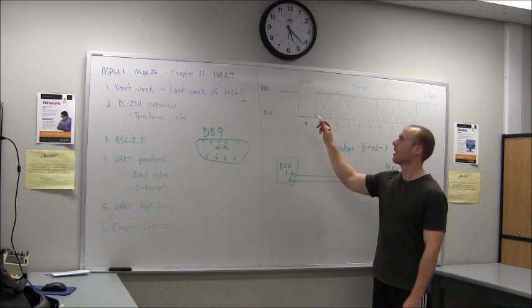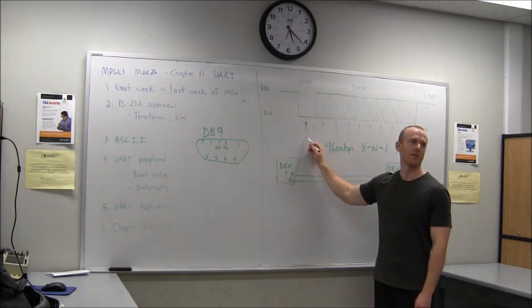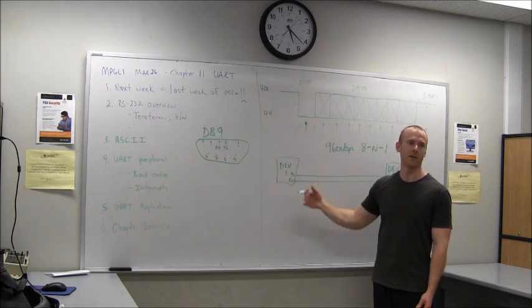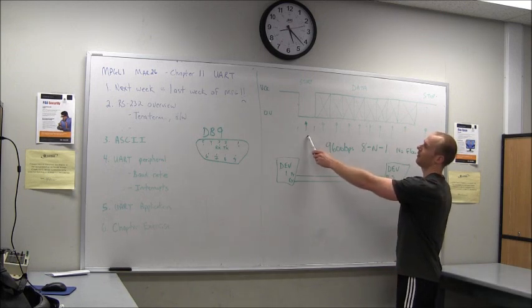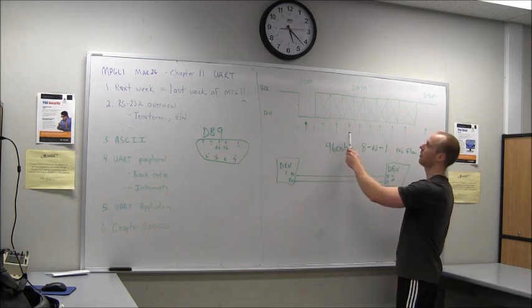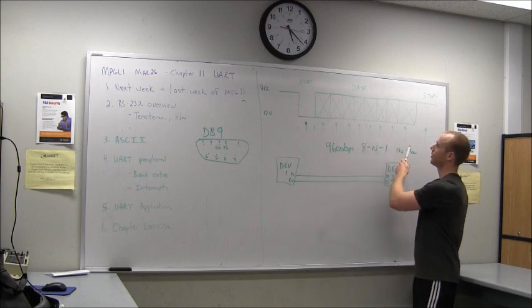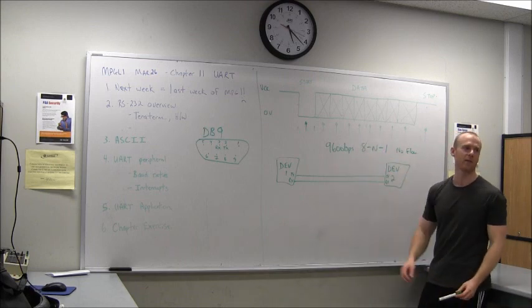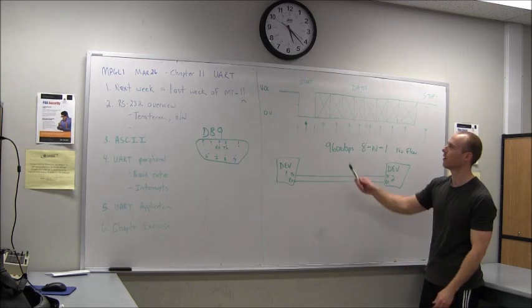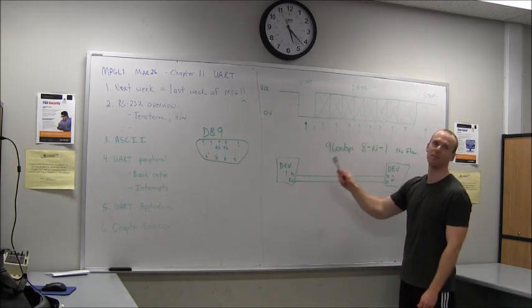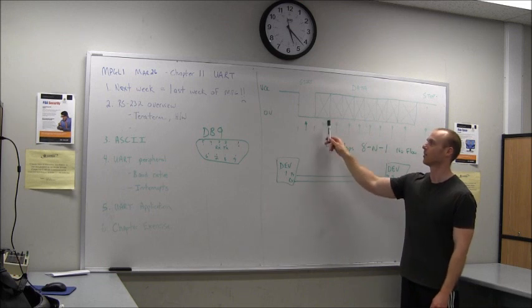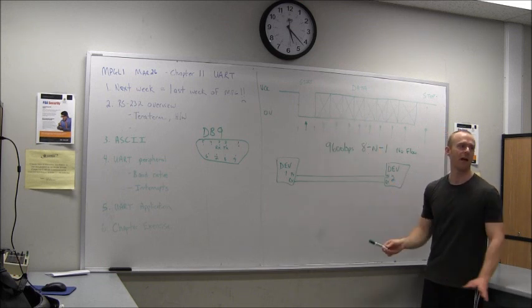So you get a trigger, and the first thing it looks for is a start bit. By the protocol definition, you should have a 0 first. Okay? If it doesn't, then you have an error on your bus. As long as you've got the right start bit, it'll continue to sample on each of the next intervals for however many data bits you've specified. As long as your clock is correct on both sides, and this frequency is the same on both sides, then this sampling point is going to wind up right smack in the middle.